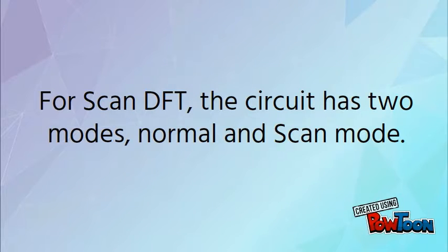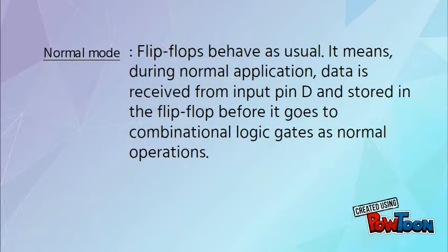For scan DFT, the circuit has two modes, normal and scan mode. In normal mode, flip-flops behave as usual. It means that during normal application, data is received from input pin D and stored in the flip-flop before it goes to the combinational logic gates as in normal operation.